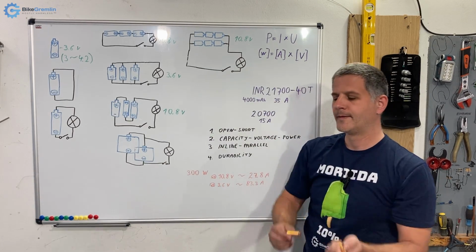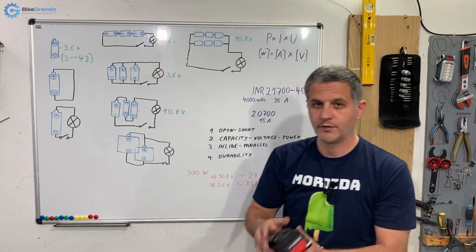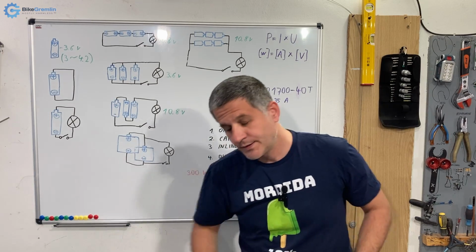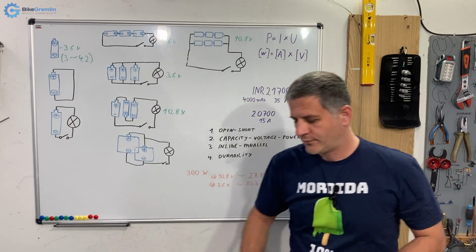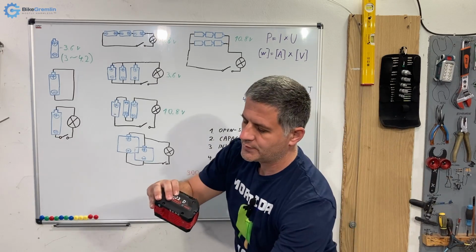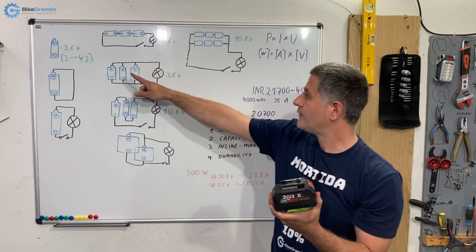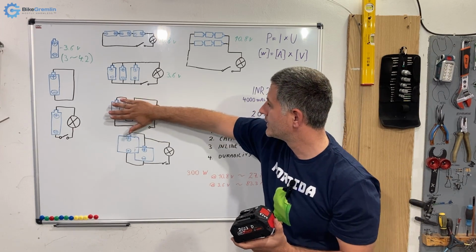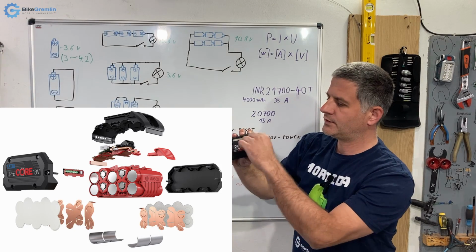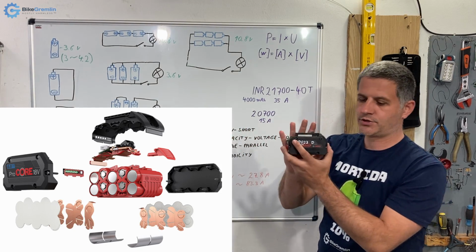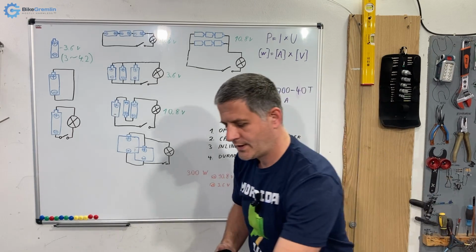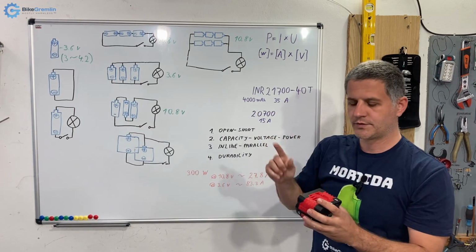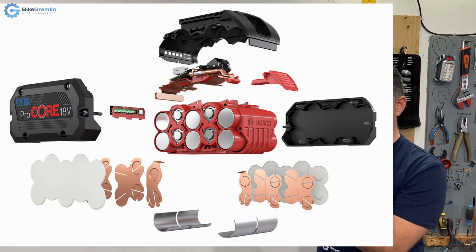Here I have only 4 to show you, and that is what Bosch did and most other manufacturers. They have 5 cells, and they've also stacked them. For example, this one is 8 ampere hours and it uses 2 rows of 5 batteries. So it has 5 lined up in line, and then another stack just over it in 2 rows, and that's why you get so much capacity and power. Their 4 ampere hour batteries have only 1 row of batteries, but here I will try to post a picture showing what this looks like when it's open.